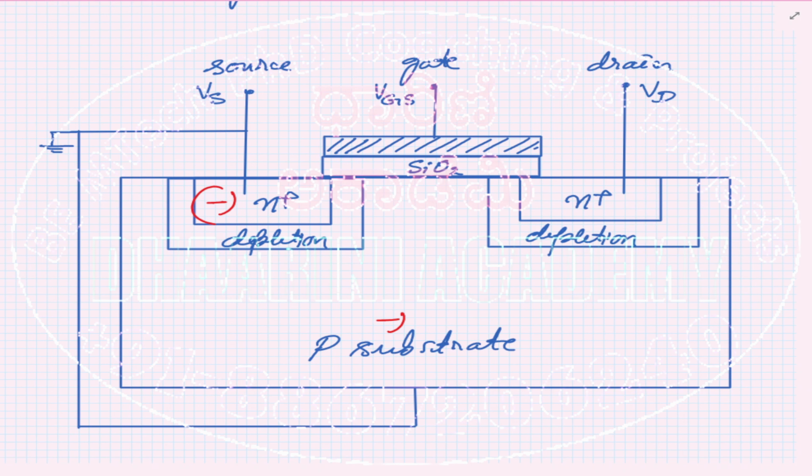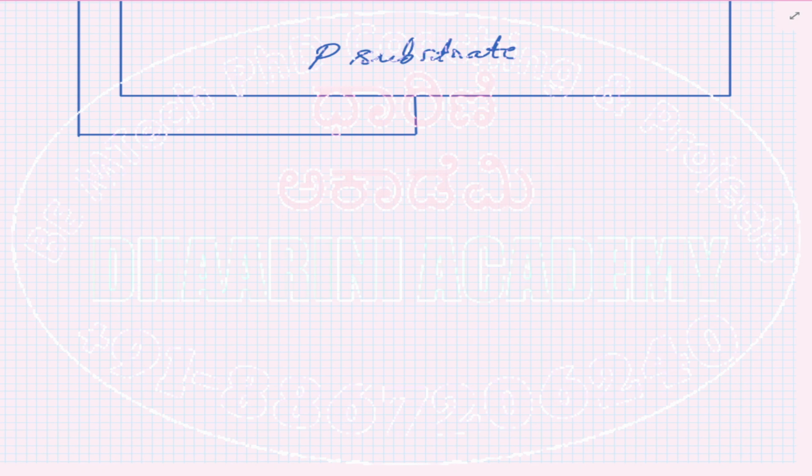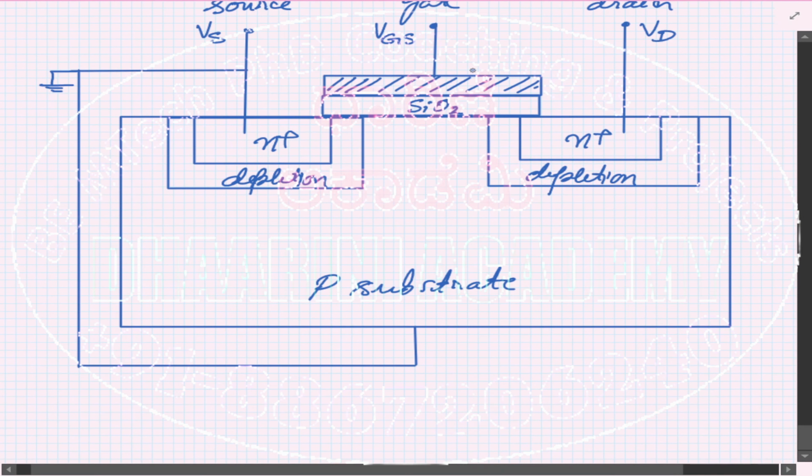Actually this depletion layer takes a lot of responsibility in deciding whether to conduct or not. That's why we have to deal with the depletion layer when we discuss this. So in this enhancement mode, this is the enhancement MOSFET. I don't see any channel there, correct? In this kind of enhancement mode, normally we have the gate region which has a polysilicon. Below that I have a SiO2 that is deposited for insulation purpose.